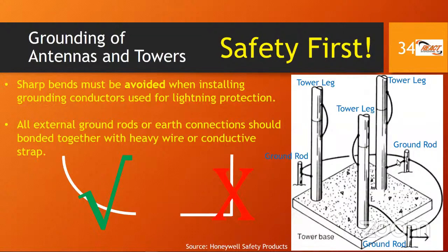Also, we need to know that all of these ground rods, so you have a ground rod here, a ground rod here, a ground rod here, we need to bond them together, and we need to use heavy wire or conductive strap. So make sure we have a nice connection between the ground rods. That is called bonding of the ground rods.